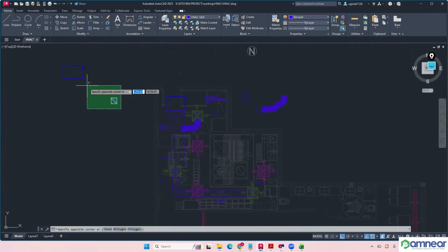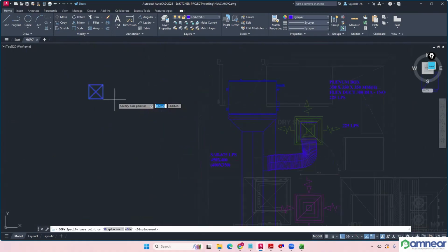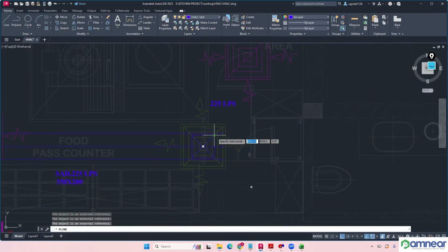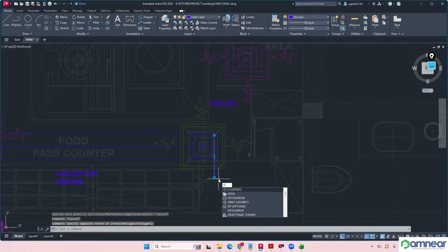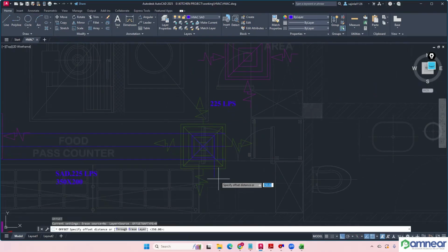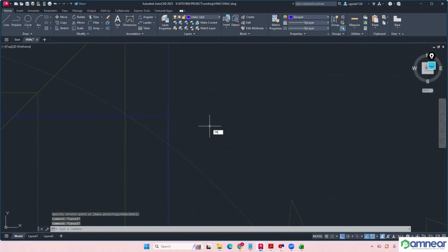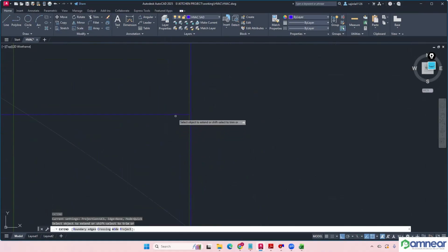And the next size we have already selected before. Copy. Okay. Now after the drop, you can extend up to maximum 12 inches, not 24. 12 inches means like 300 mm, but 150 is fine. I'm going for 150 mm. Enter. Okay, so just fillet radius 0, you can apply. Now TR double enter, it is not extended, right? So EX, TR double enter.